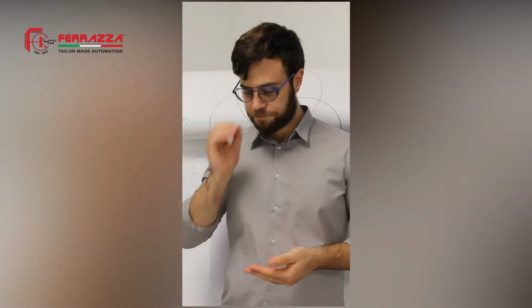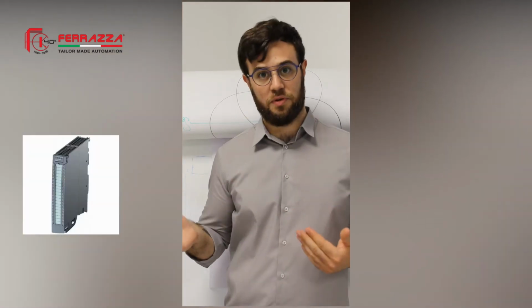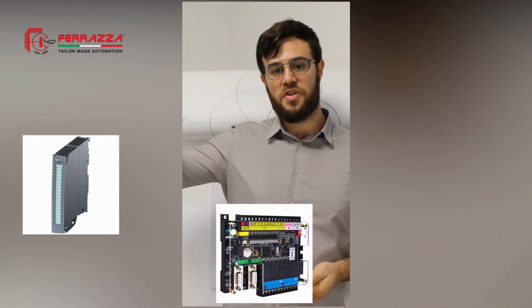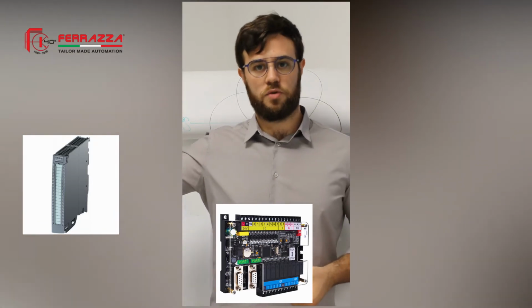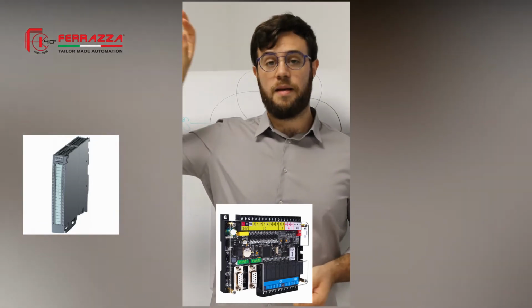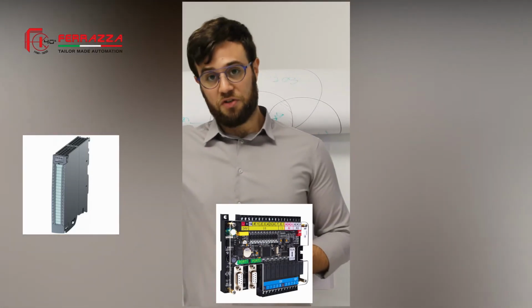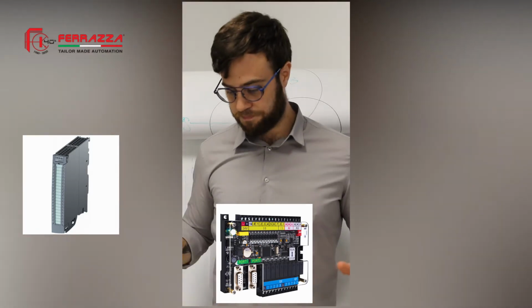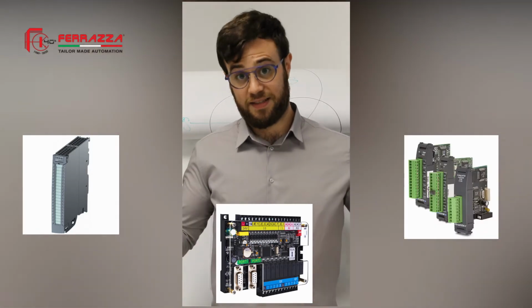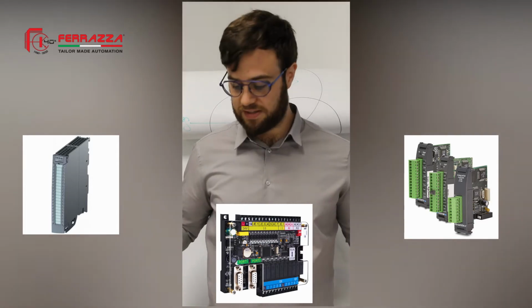How does it work? Well, a PLC, as soon as the plant is started, starts its activity by scanning all the analog and digital inputs and memorizing the status in what is called an input record. The CPU then analyzes all the commands, all the controls that are transmitted into the PLC and memorizes them in the output record. Such content is then transcribed to the physical outputs of the PLC, meaning they are activated.